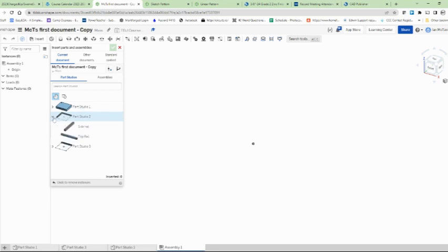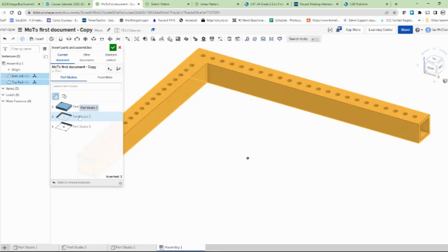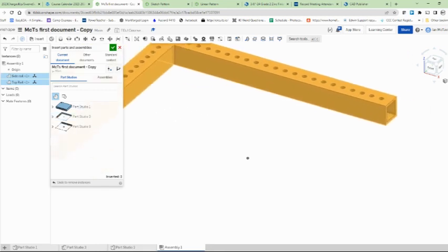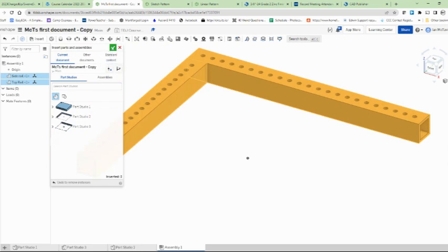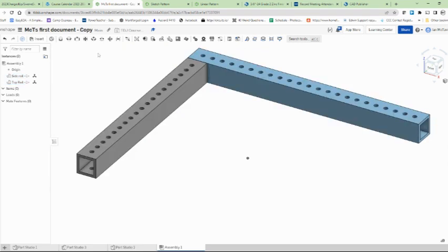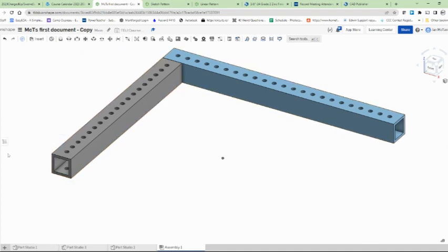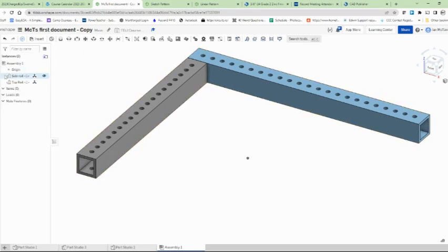Instead of clicking the individual parts, we'll just click the Part Studio, and we will just go to the green button. You'll notice you can move it around, but we don't want to do that. So we're just going to go up to the green button. And over on the left, these are our instances. And I've had a couple students accidentally close the instances section. So that little icon allows you to open it if you accidentally close it.